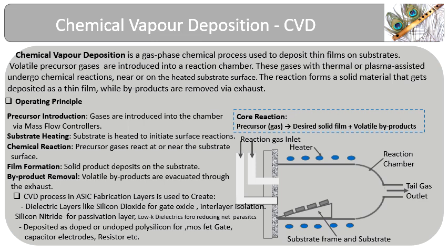The solid material deposits on the substrate, while the byproducts are evacuated by the vacuum system. CVD is widely used to deposit dielectric layers like silicon dioxide and silicon nitride, as well as polysilicon, tungsten, and barrier films. It offers excellent conformality, making it ideal for coating high aspect ratio structures and complex geometries. In MOSFET fabrication, CVD is critical for gate dielectrics, spacer formation, and interlayer dielectrics.